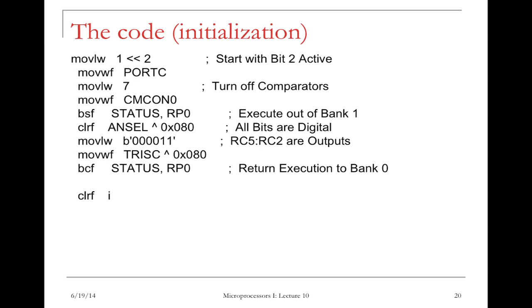All right, this TRISC, tri-state C. If I mark these bit positions, just didn't write down. This corresponds to these 4 bits, corresponds to these 4 pins. This ANSEL will make these as digital pins.